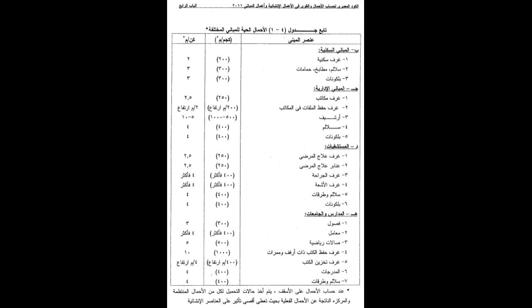So the code defines this as 200 kilogram per meter height. So if you have shelves at full floor height, say 3 meter, you multiply 200 by 3, it is 600 kilogram in this area. This is, we say, for filing.